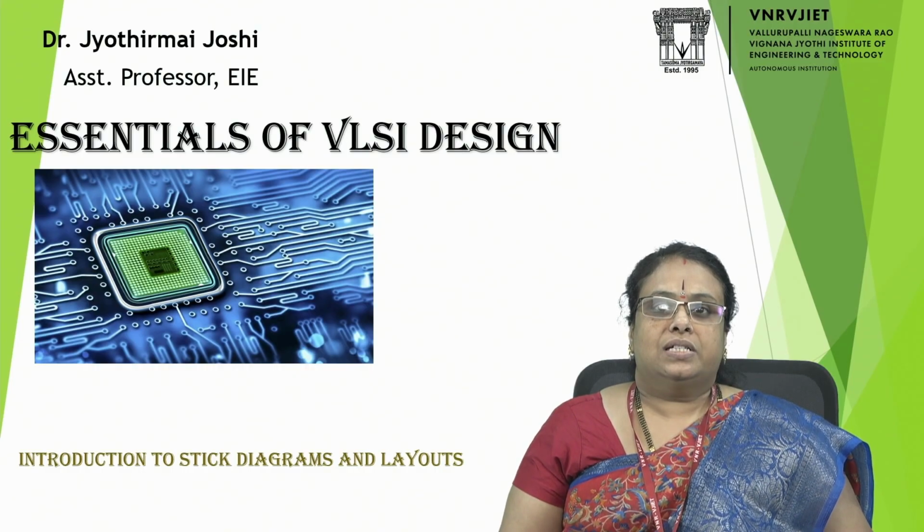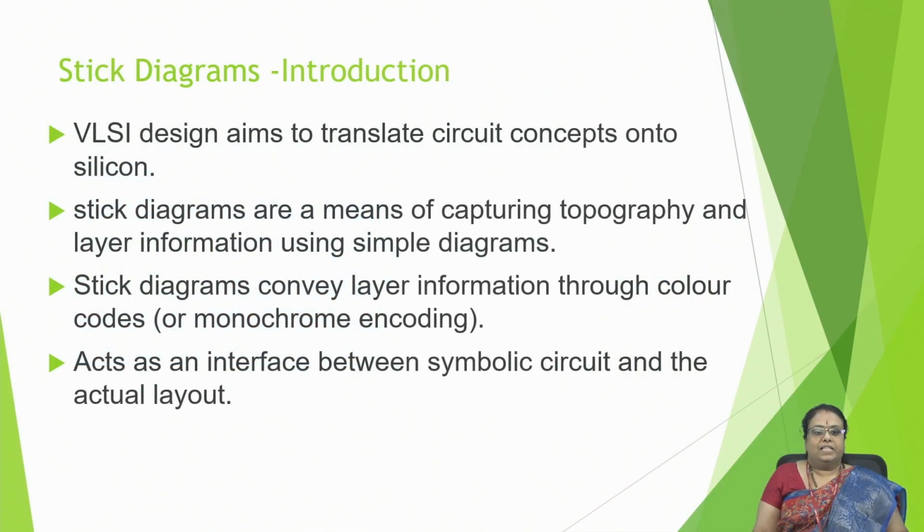Today I want to discuss the introduction to stick diagrams and layouts. So basically, what are stick diagrams? Stick diagrams are generally representations of the IC VLSI design process. VLSI design aims to translate circuit concepts onto silicon. Stick diagrams are a means of capturing topography and layer information using simple diagrams.